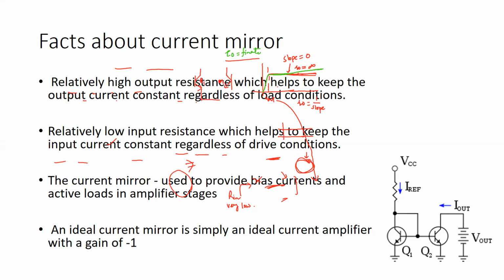Then you have, let's say, emitter resistance Re, and you apply input V1 and here input V2, and usually you connect the resistors to VCC. So these resistors RC1 and RC2 act as a load, but current mirrors can be used as an active load. Instead of the resistors, you replace them with these transistors as a current mirror.